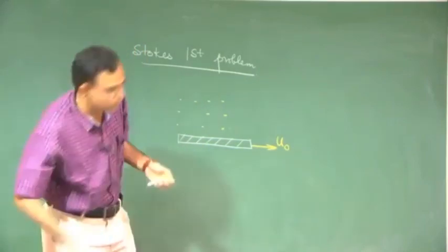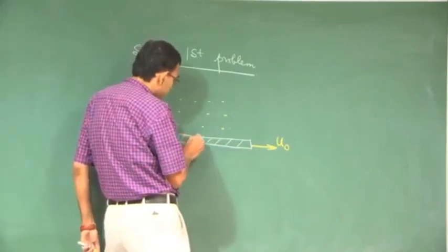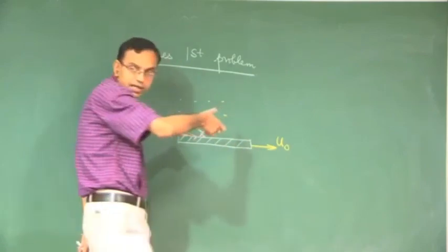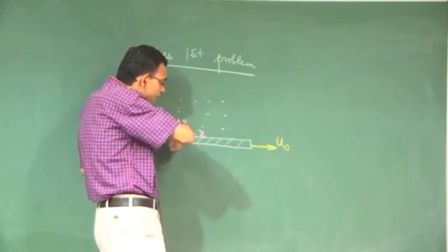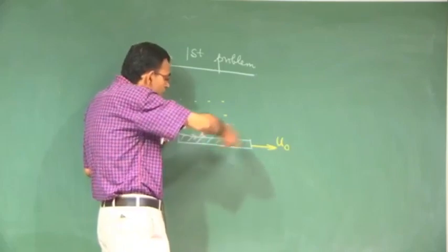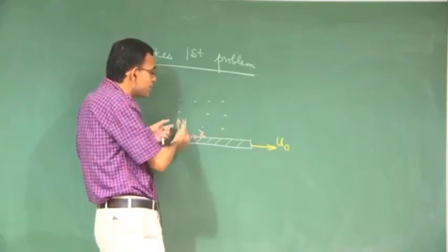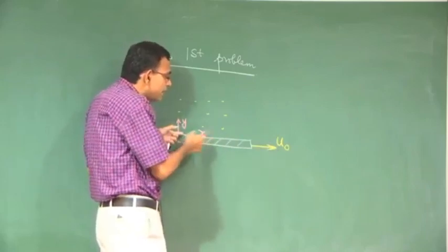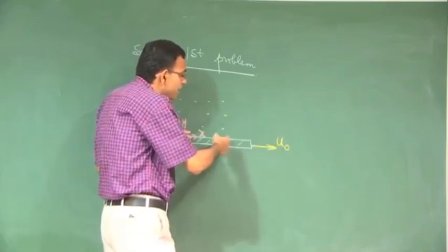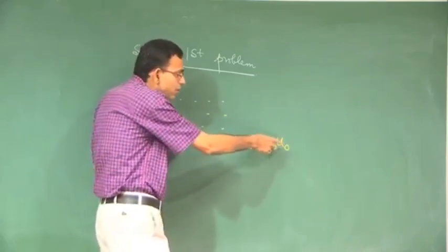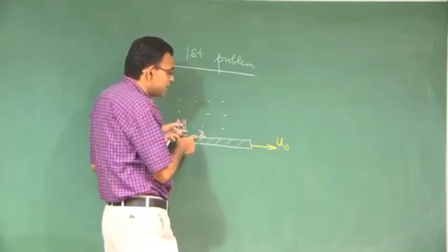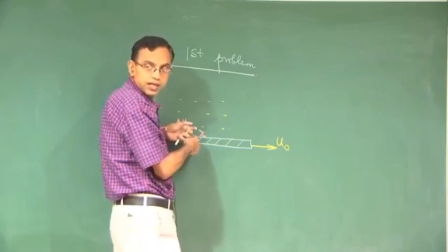Now if you think of a coordinate system x and y, because the plate is pulled along the x direction, the predominant effect is the velocity along x, but the variation is with respect to y. When can variation of velocity with respect to x occur? It can occur had this u0 been a function of x, but the pulling velocity is not a function of x. Because of uniform pulling along x, this problem has a translational invariance with respect to x.